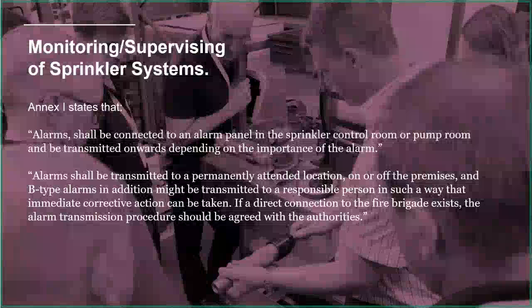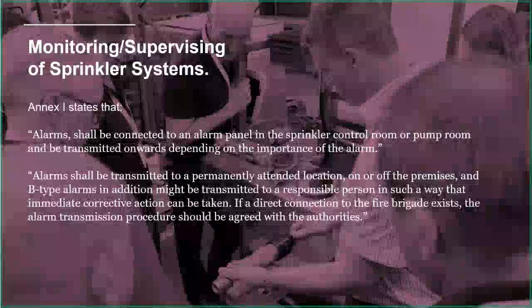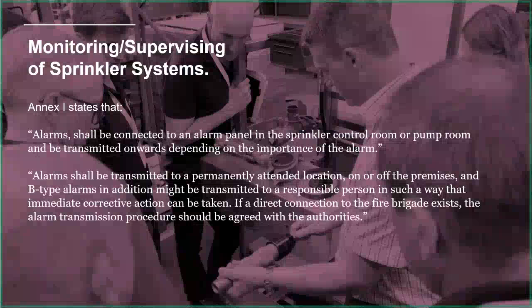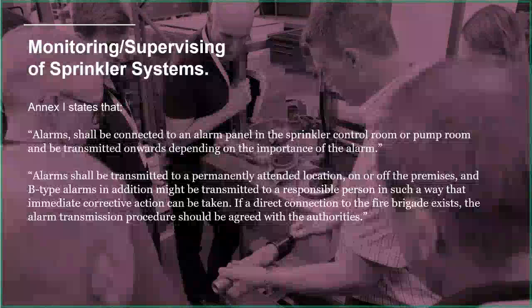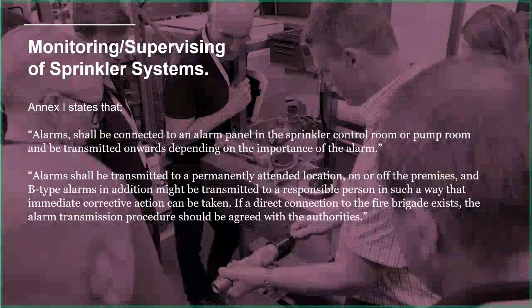Alarms should be transmitted to a permanently attended location on or off the premises, and type B alarms in addition might be transmitted to a responsible person in such a way that immediate corrective action can be taken. So that's kind of interesting that even back in 2015 when this annex was first written, we had this idea of basically sending text messages. That's for me what it boils down to, is kind of having a responsible person that they're going to have a remote kind of access to these alarms. Obviously this is optional, but it is useful.